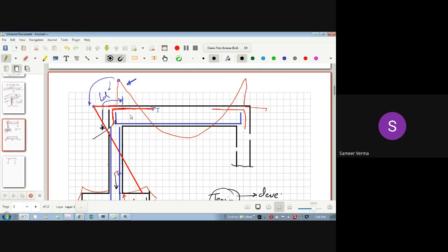Excuse me, sir. Yes, I have a doubt. Yeah. So the general doubt, not regarding this. If you are talking about the tension, if we pull out the bar and if we provide sufficient LD, it will not fail in LD, but it can fail in flexure tension, the reinforcement. So we don't have to take both into account, LD and flexure tension failure? We have to take both.